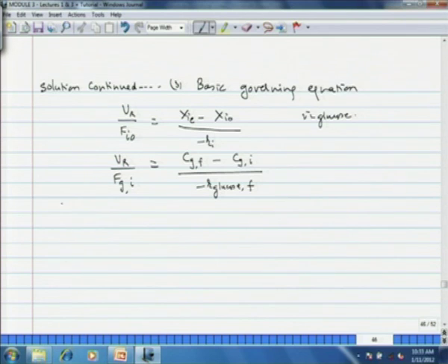Now we know that CGF, the final concentration of glucose, is 0.75 kg per meter cube, and then we substitute all the values. Remember here that the concentration of the microbes, the Saccharomyces cerevisiae, has been raised 10 times to 0.95 kg per meter cube.